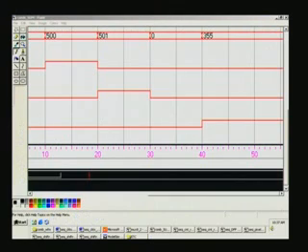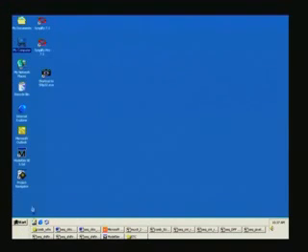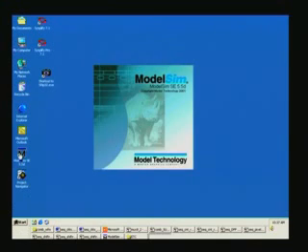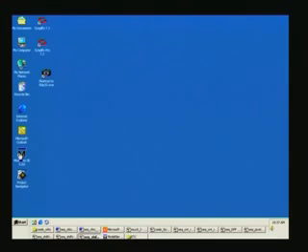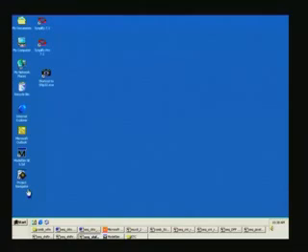And before this, we'll have a look at ModelSim once again. You also said the output can be viewed as a binary string. Suppose I have 16 outputs. Yes. I can't see, instead of seeing 16 waveforms, I can club it together and make it as a binary, and we are going to see it now. Okay. Right? So when we touch the shift register, you will be seeing that precisely.